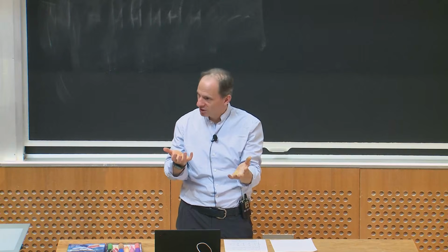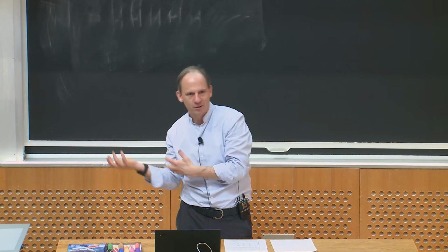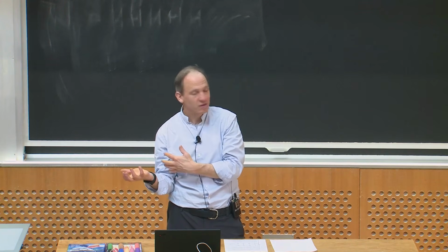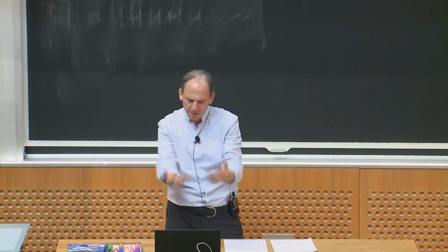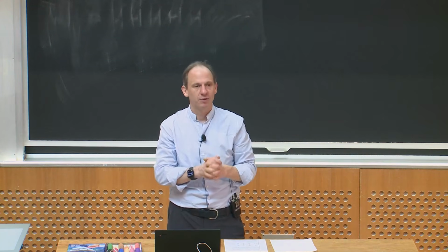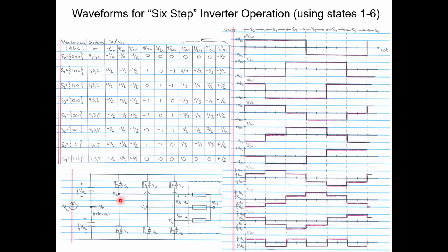Now, if you're going to put notches in the waveforms, you wouldn't try to eliminate the third harmonic, because the third harmonic is going to go away. You might try to eliminate the 5th and possibly the 7th harmonic, right? So the same kind of games we talked about playing with a single-phase inverter, you can play with 3-phase inverters. It's just you're doing each phase and then you're shifting that by 1/3 of a cycle to get to the next phase. Okay, any questions about that?